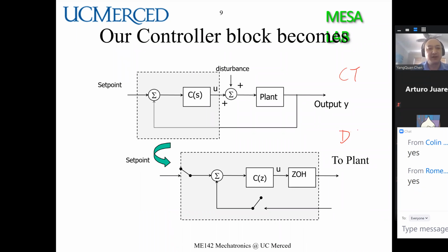So control in the continuous time domain is the CT domain. This is the discrete time domain, digital. The difference is: this is analog, this is digital, this is digital, this is also digital, but now with a zero-order hold, this is analog. This is a DAC, this is an ADC. This thing is called a sampler: sampling of these continuous signals. We're going to explain that.